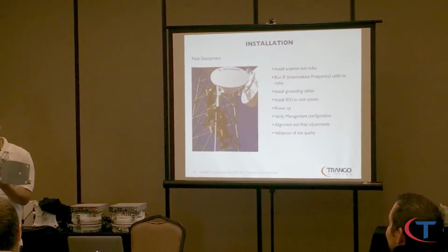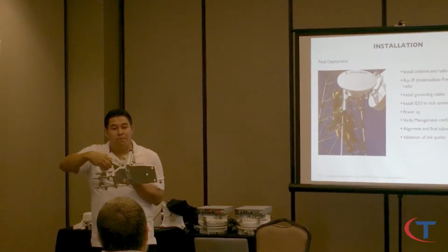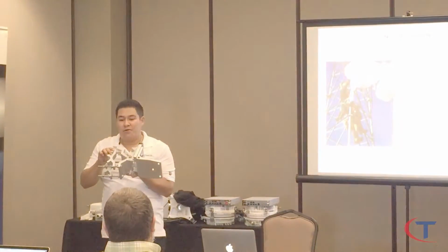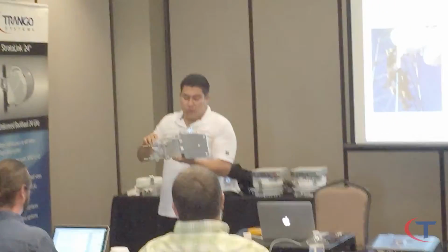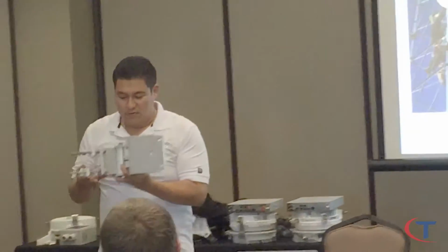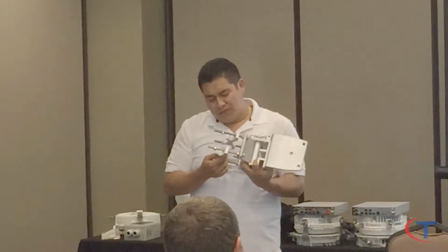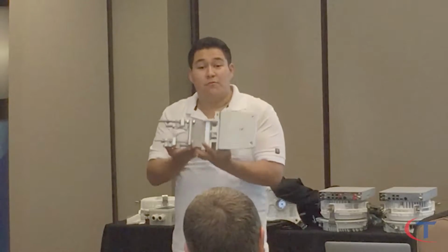So look at the actual design of this. This can accommodate a thicker pole mount. You flip it around for a smaller pipe diameter. Now, when you do the rough alignment, you're literally going to have to move the entire structure left or right. A good tip: some mounts come with pipe clamps, so that when you loosen this, it doesn't go down on the pole itself.